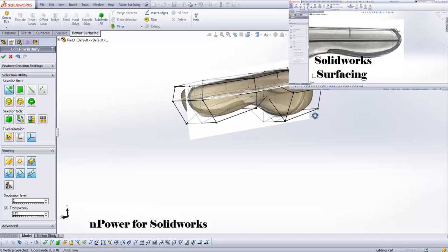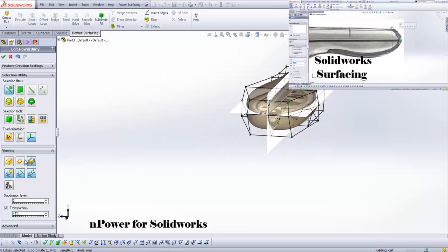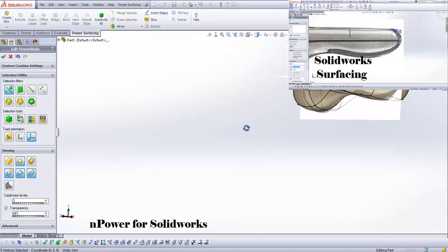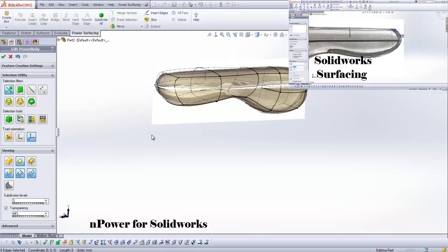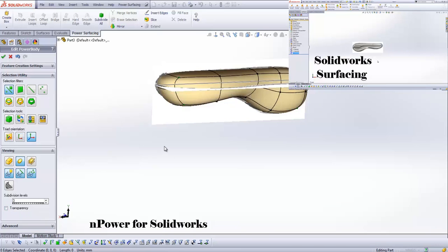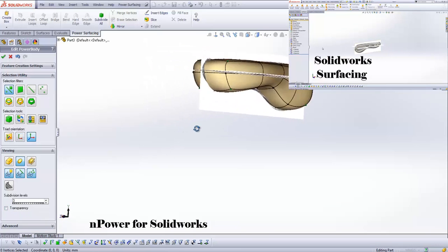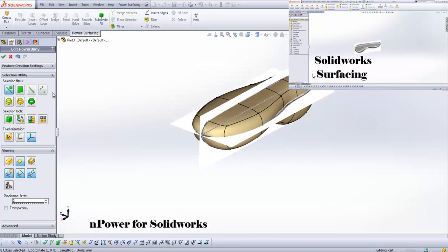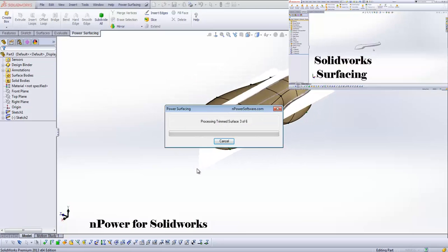So I'm at this point selecting edges, excuse me, it's behind the screen there, and just scaling those in. I'm just tucking in the bottom and the top a little bit to try to get the shape that I'm looking for. I don't have a sketch that goes through the cross section in the other direction, so at this point it may not be critical to me. I'm just shaping that in. Switching view modes, I can see just the sub-D model itself. That way I can get a cleaner look, and that looks about where I want it.